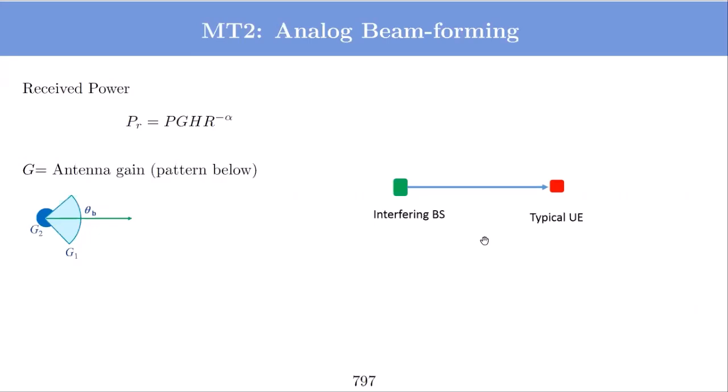Similar is the millimeter wave case. You have an antenna, and by steering it mechanically or electrically, you can focus beams into different directions. But since it is analog beamforming, you don't have the capability to have different streams beamformed to different directions.